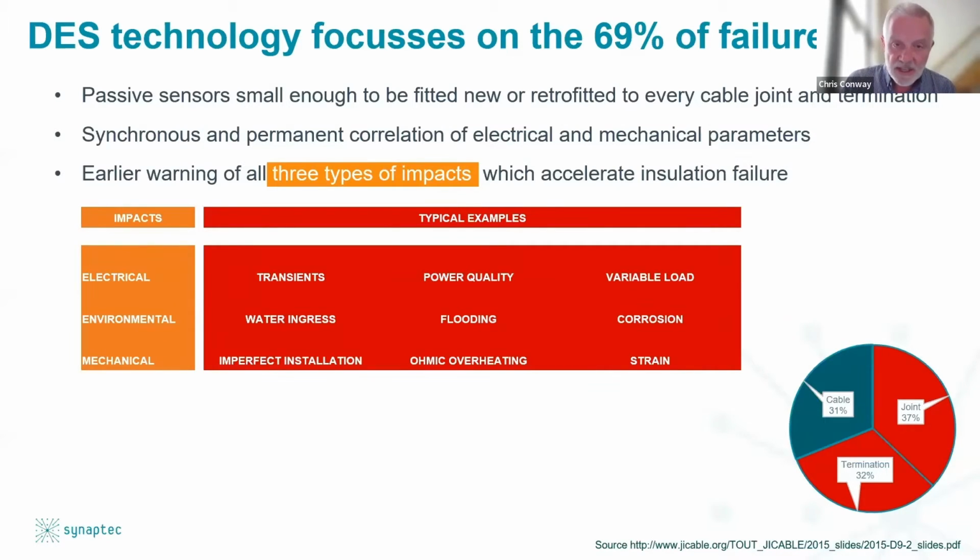Subsea cables deployed in offshore wind farms have to endure a uniquely harsh environment. It's not solely due to the salt-laden atmosphere and the constant pressure of water ingress into cable infrastructure. Terminations are a relatively weak point throughout wind farms, as they become a focus of electrical stress, resulting in ohmic overheating and degradation. This harsh environment, with fast transient harmonics, is continually stressing and wearing cable infrastructure.